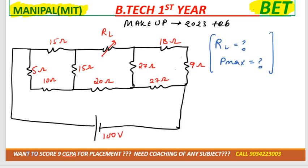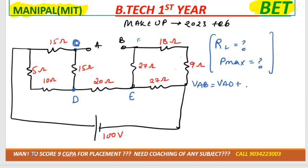So in the very first step, RL must be open circuit, right? So I'm doing open circuit. This would be A and this would be B. So you can mark this point as C, this point as D, E, F. Or we can do the same thing, A to D, D to E, E to B. So VAB would be equal to VAD plus VDE plus VEB.